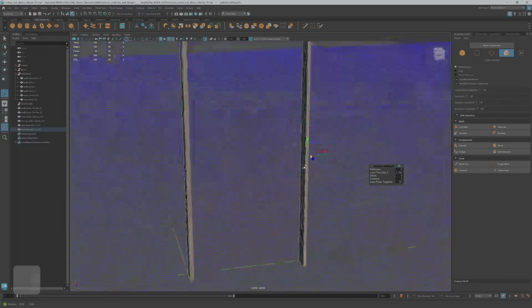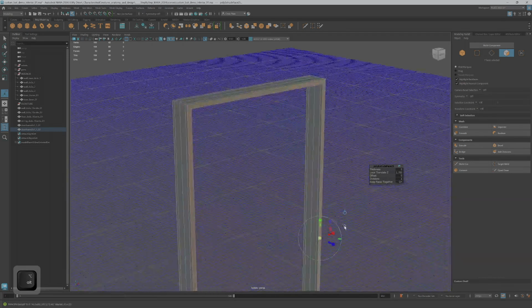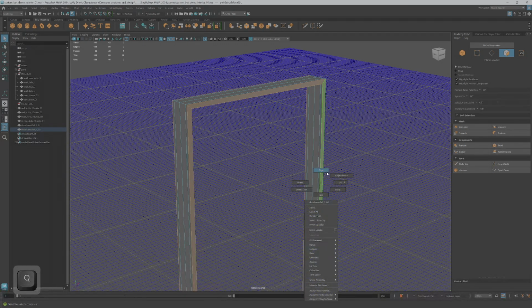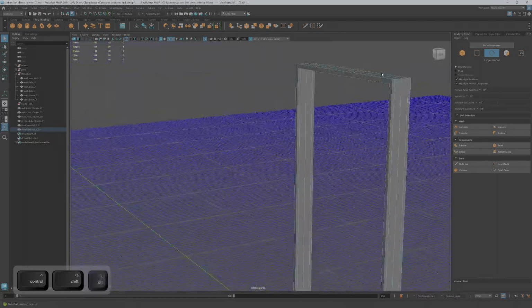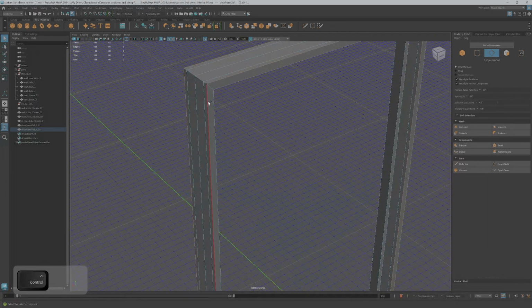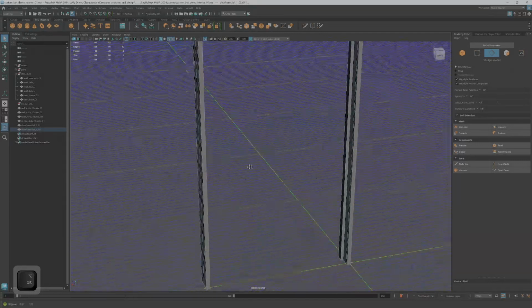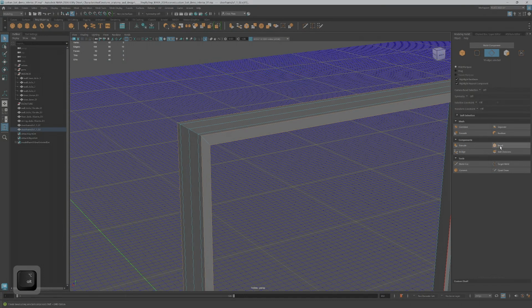And then afterwards, let's go to the scale tool and just scale them down just a little bit. And looks like that could be problematic, so we'll just leave that for right now. And go back, we'll grab the edge. And this profiling here, you don't have to do. I'm just kind of showing you if you want a little bit of the milling. These are little strips that go around the edge of your windows and doors. Sometimes you could see it on your furniture. And we'll do a bevel on that.